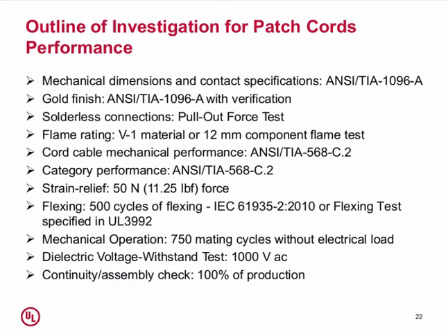So just a brief rundown of what's in the specification. As I showed the drawings earlier from TIA 1096A, the outline requires the mechanical dimensions and contact specifications that are in TIA 1096A. In this case, there's no reason to reinvent the wheel. 1096A has been around for a long time. A number of manufacturers have verified that things like the dimensions and the gold plating requirements are valid, useful, makes sure that the quality in the plugs is going to be there, so we just use those.